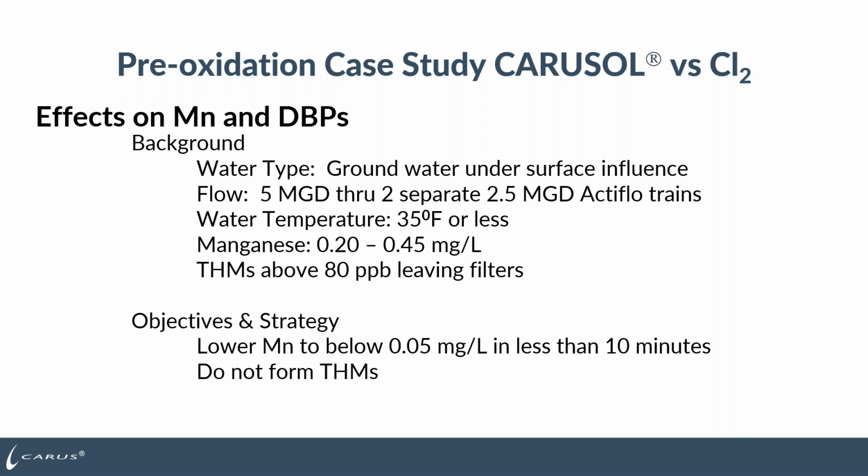It was a unique treatment process because it was an active flow, which is sand ballasted coagulation. So they treat water and filter it in a very small footprint before they go to filtration. So typically there's not much contact time in the plant. They're not the standard flocculators with 15 or 30 minutes in a settling basin with multiple hours. In this type of plant, typically from the front of the plant to the back of the plant, there'll be 15 to 20 minutes of full contact time.